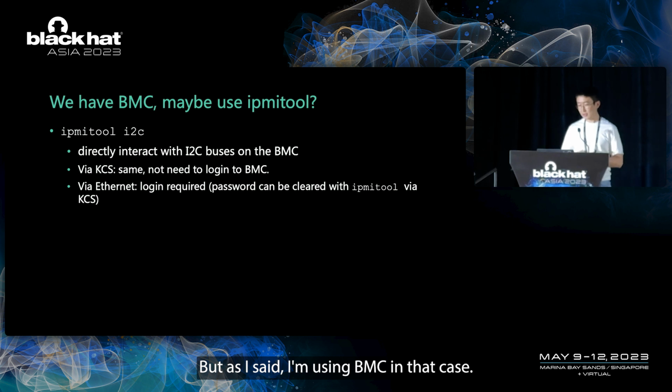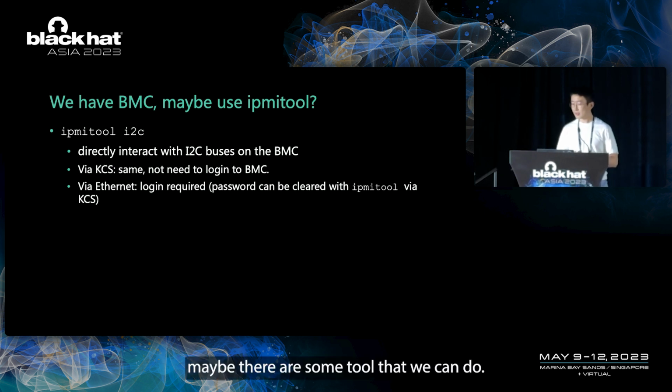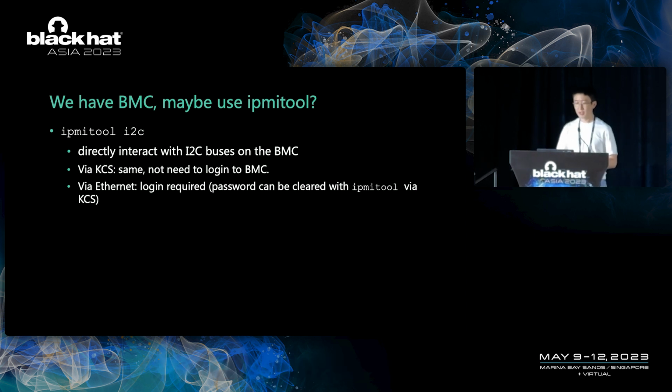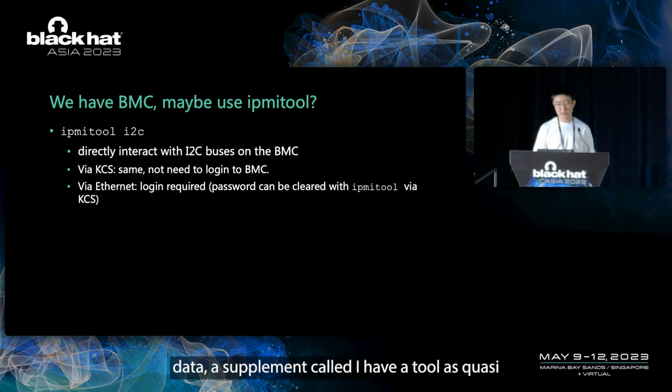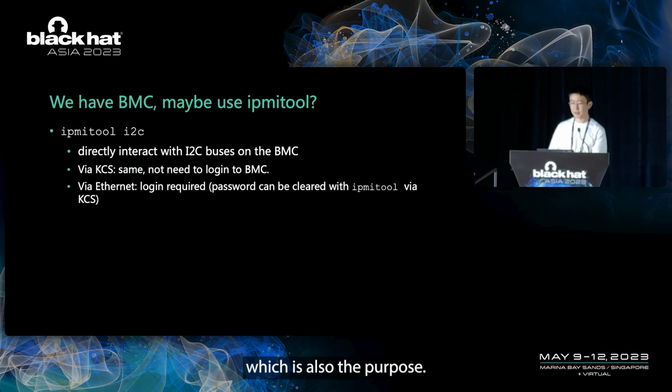But as I said, I'm using a BMC, since it's a server platform, so maybe there are tools that can directly interact with the BMC. We found there is an ipmitool, with a subcommand called ipmitool i2c. It allows us to directly interact with the I2C bus on the BMC, which is also the PMBus.